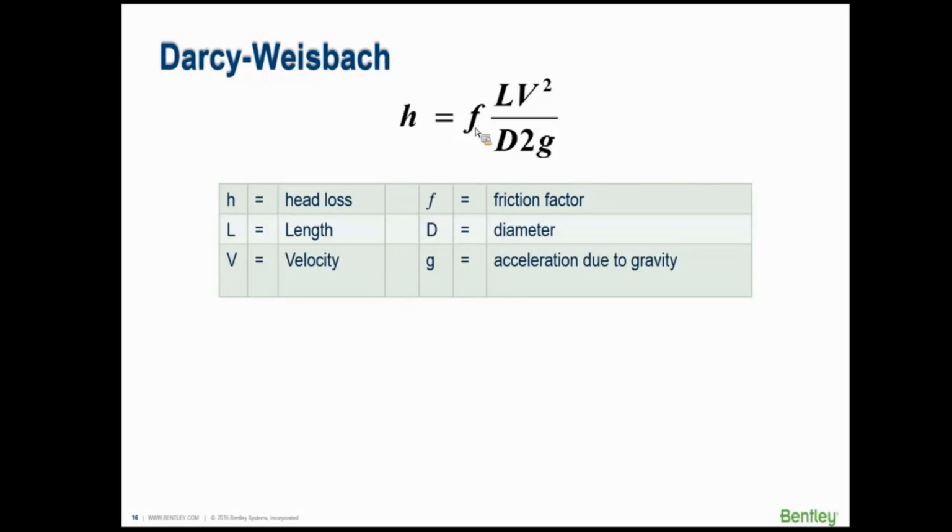It was really the German scientists under Prandtl, around the turn of the last century, who came up with some very interesting experiments where they would glue sand grains on the insides of pipe, and run water through those sand grains and figure out, depending on the size of the sand grain, how much the value of F changed. It was some really interesting research from really smart people.